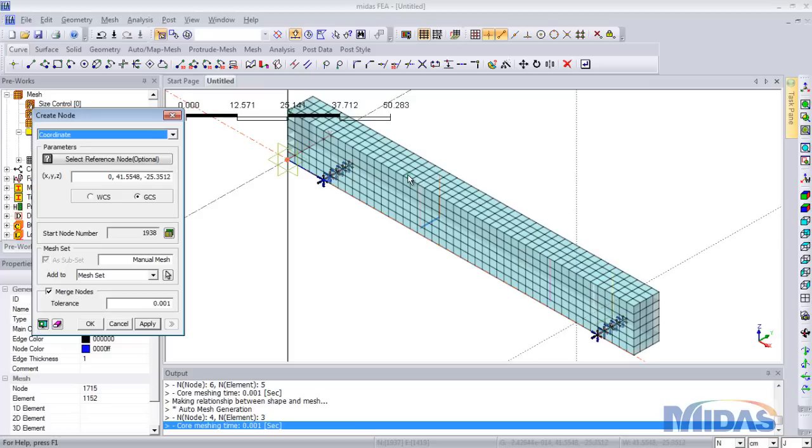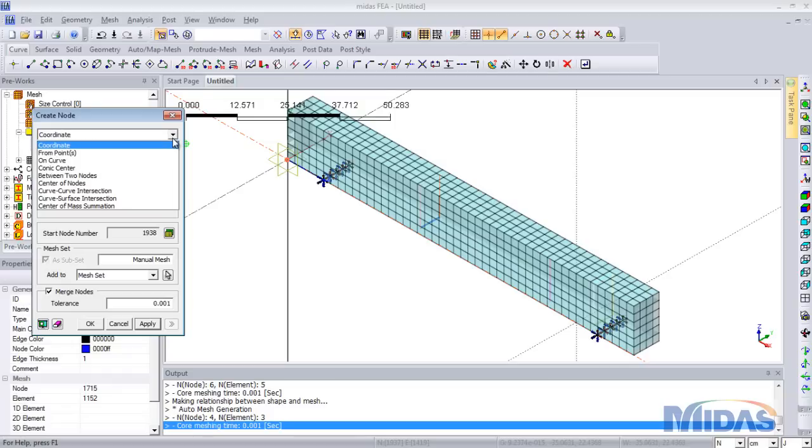If we are not using the rigid link and we are providing the prescribed displacement of the same magnitude on the nodes lying in the same plane and the same line, the results would be the same. In the end, as I have done some tests and analysis, I would be showing you the comparison of the results as well. It is actually the user's choice what is more convenient. In certain cases, when the loads to be applied are many in number, and sometimes we require to change them, it is more convenient to create a rigid link and apply the load on one single node, so that in the future if we want to change it, we can change it with quite ease.